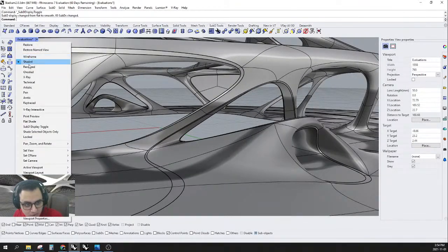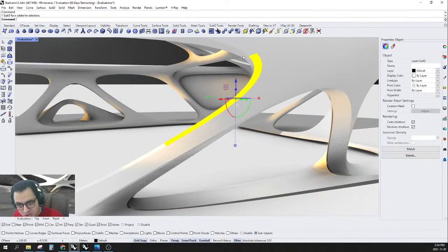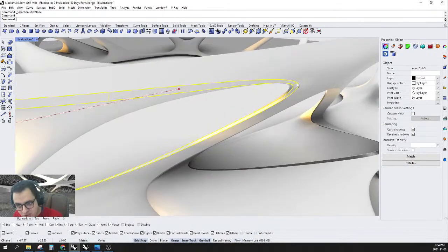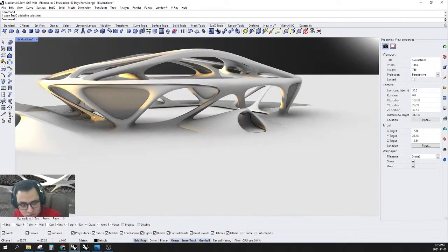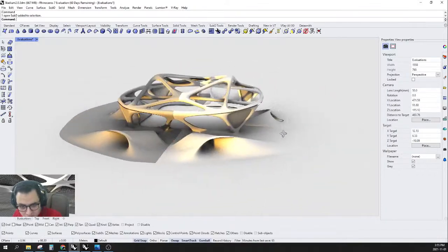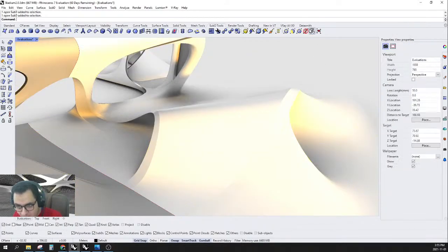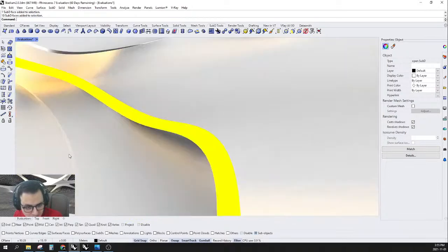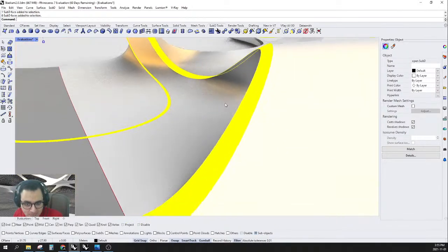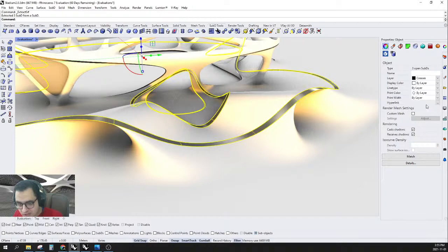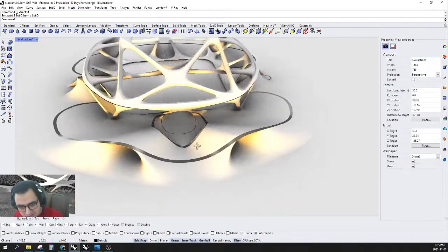Let's see which parts we need to fix. So now I will simply select these and extract them, and after extraction I will select them again and go to creases, so it will look like this. Looks kind of interesting. Of course we need to mirror what we did. Again, we need to select these, double click, and select these, double click, and of course select these, double click and extract all of them, and maybe move them to the creases. Perfect, so they will look like this.